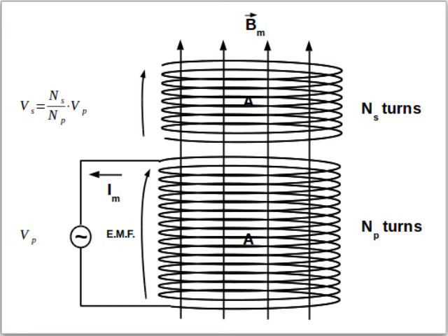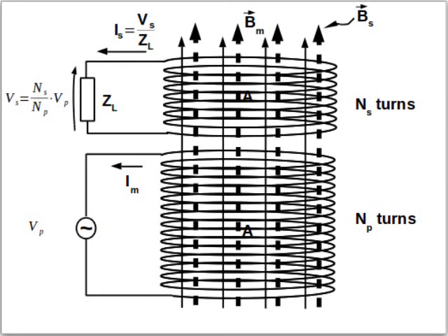The other half happens when you connect a load to the secondary. This will make a current flow, which will generate another magnetic field. If this is a changing magnetic field, it will tend to generate a counter-electromotive force on all the loops of both windings. But wait, we have a voltage source connected to the primary which will not tolerate any other voltage to be there except for the one it imposes.